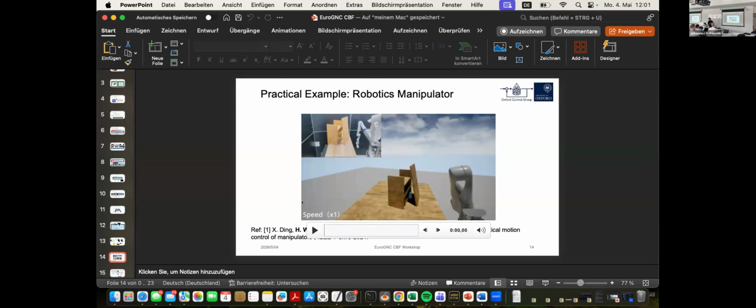Sure. For this case, because we are controlling the end effector of this robotic arm, the camera is placed very close to the end effector. We store the points on the boundary of the obstacle, so there is a historical data set of boundary points of the obstacle. With all this historical data, all you need to do in the following semi-definite program is take care of all these obstacle points. But the cost is that you are growing the dimension of the SDP with time.